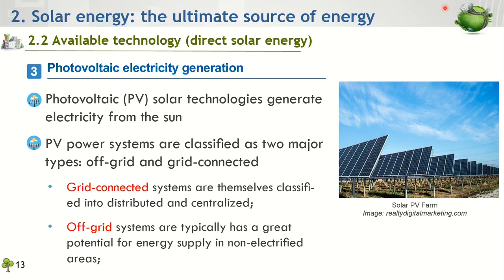The grid-connected PV system connects and provides power to the utility grid, which can be a distributed system made up of a large number of small local power plants, or a centralized one that works as one large power plant. In contrast, off-grid systems are typically standalone systems, which generally require an electrical storage element or backup power. It can provide relatively small power capacity and is connected to electric appliances directly. One of the advantages of this type of PV system is that it allows easy mobility.